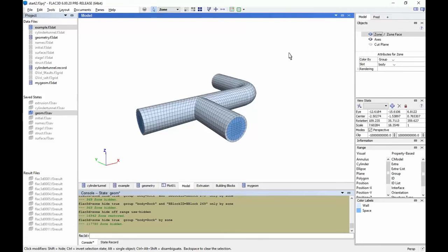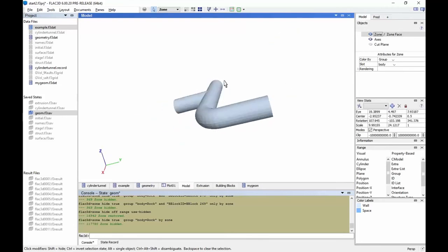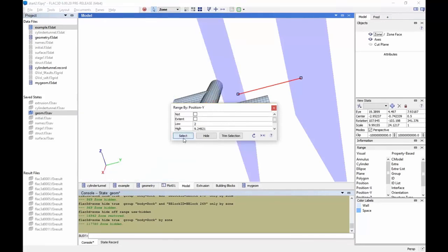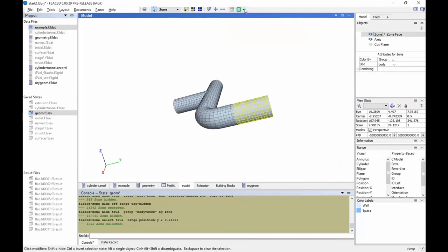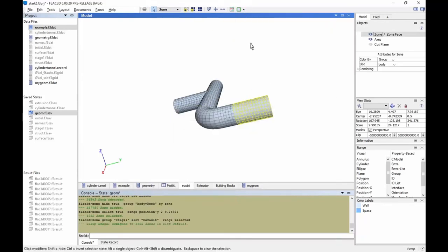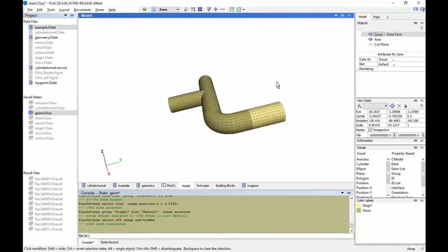Okay. And you can go on to select regions. So in this case, let's say that I want to do a staged excavation. So I can bring up here a general range, which I can either mess with interactively or type in. Select that, and then here I'm going to give that a name, stage 1. So those have now been labeled stage 1. You can see that here for reference later when you do an excavation.